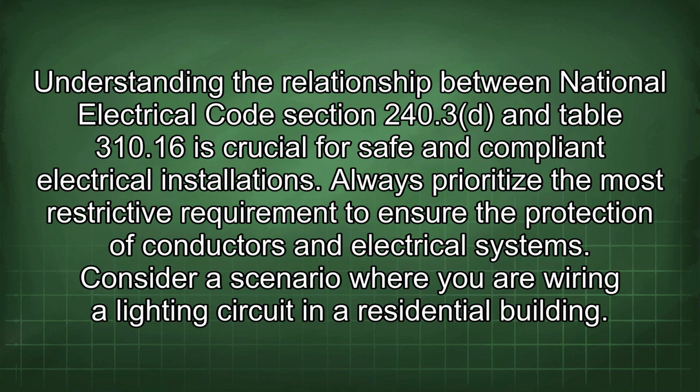Understanding the relationship between National Electrical Code Section 240.3 and Table 310.16 is crucial for safe and compliant electrical installations. Always prioritize the most restrictive requirement to ensure the protection of conductors in electrical systems.